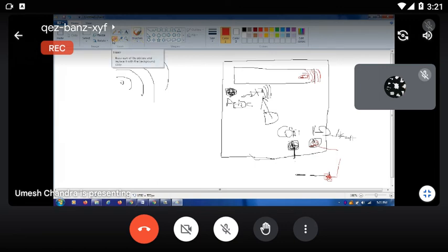Sir, why did we short circuit the two wires? We should apply a battery here, no? Battery? No. Here, short means you just check whether the probes are working properly or not. Actually, a battery is not necessary here. The battery is already in the multimeter, that's two pencil batteries.